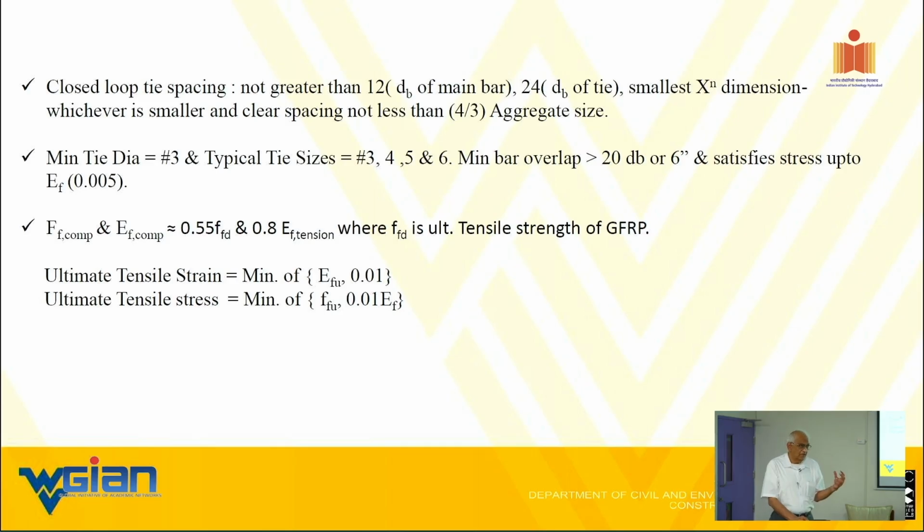even for steel you have some ASTM procedures on the aspect ratio, meaning the length versus the diameter. There it is a little bit more consistent than in FRP, because you will never get a consistent result in FRP in relation to length of the specimen versus diameter, because it is going to crush very easily due to Poisson's effect.